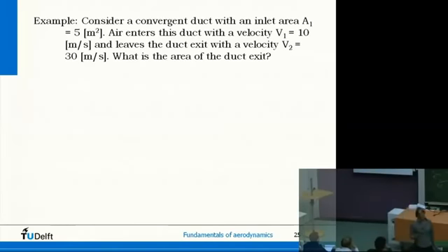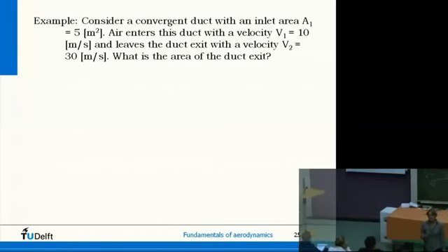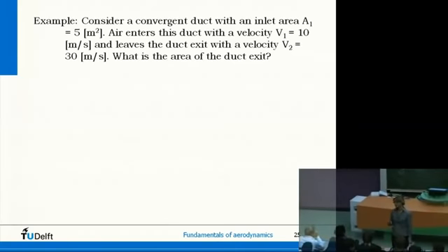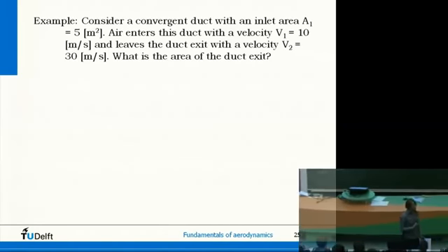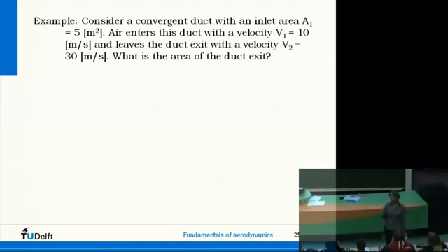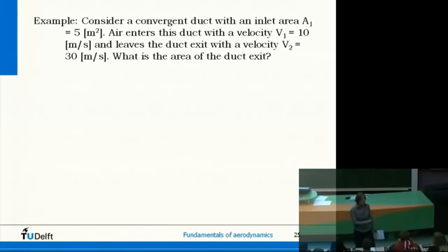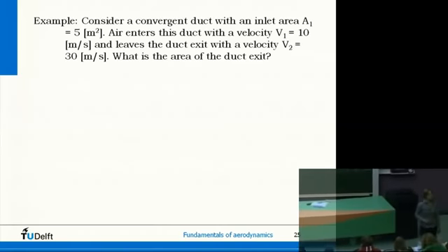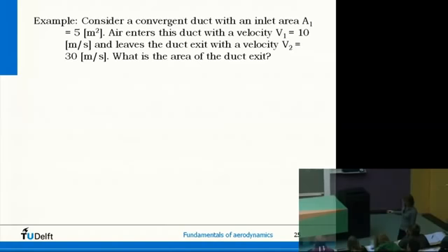In general applications, cycling, cars and gliders are really low speed subsonic. Takeoff and landing might be low speed subsonic, but cruise flight of commercial aircraft is really not low speed subsonic. Subsonic, transonic, but not low speed. So from the application, if I tell you what application it is, you can already get a hunch. Okay, that might be worth checking because you sometimes make mistakes. The area decreases and indeed the speed increases. So for low speed subsonic that makes sense.